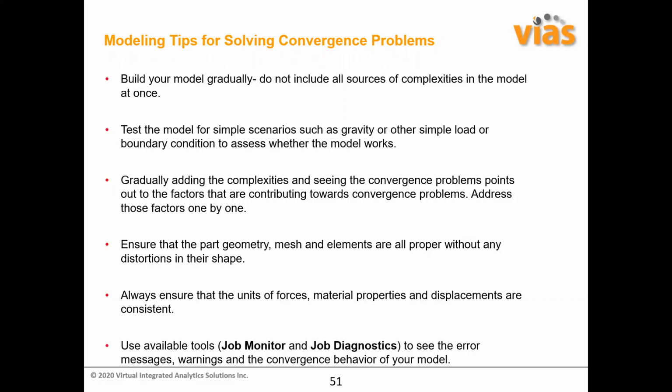Always ensure, going back to the classic point, that the units of forces, material properties, and displacements are consistent. As you are well aware, in Abaqus there are no units. So you should always make sure that the system of forces, pressures, the material data, and the displacements are in consistent sets of units. Use the available tools, job monitor and job diagnostics. Job monitor is for checking the ST and MSG files, and job diagnostics points out the physical regions in the model, to see the error messages, warnings, and the convergence behavior of your model.